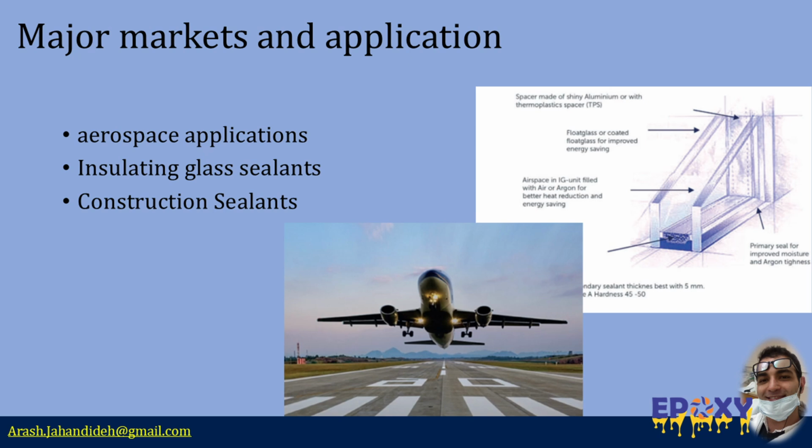Additionally, liquid polysulfides are used in the protection of secondary contaminant areas, zones designed to prevent environmental contamination from spilled or leaking chemicals, fuels, or solvents. They also provide long-lasting sealing and corrosion resistance for bridges and other critical infrastructure. Upon curing, these materials develop a rubber-like consistency with impressive resistance to both water and UV exposure, contributing to their long service life in outdoor and submerged environments.